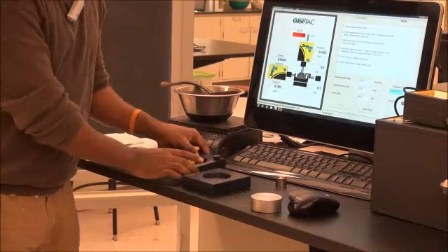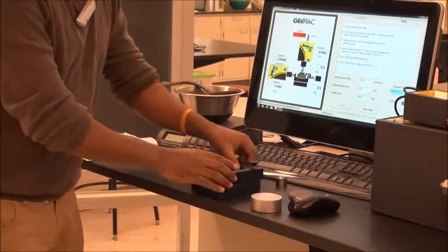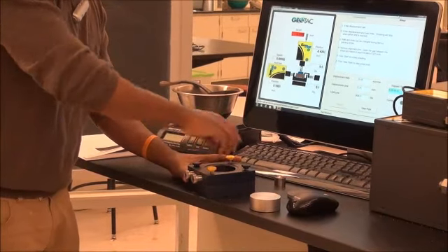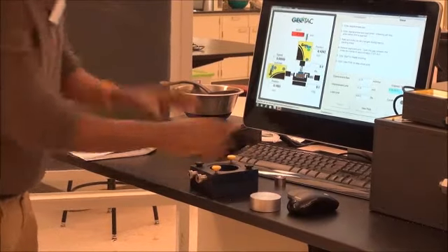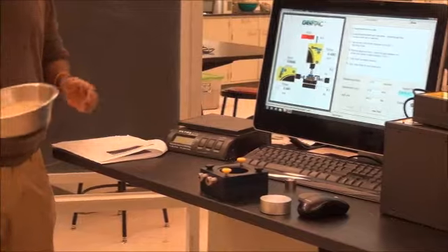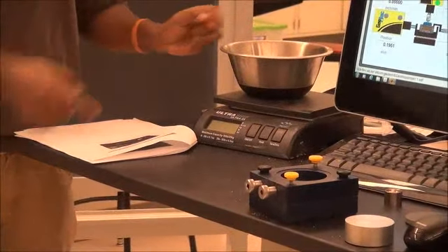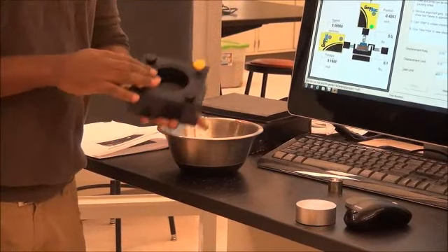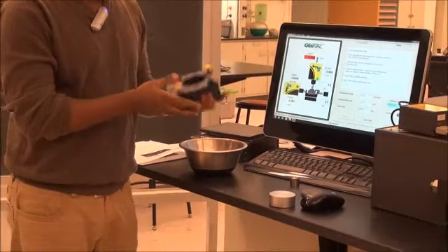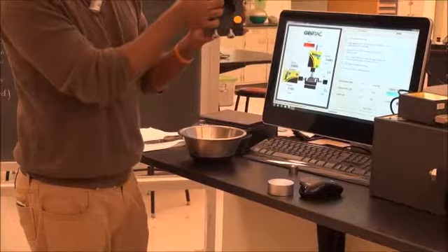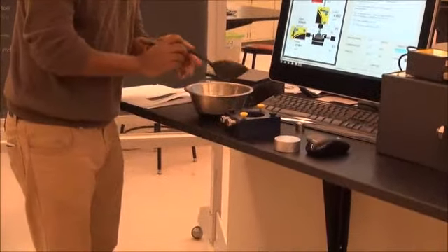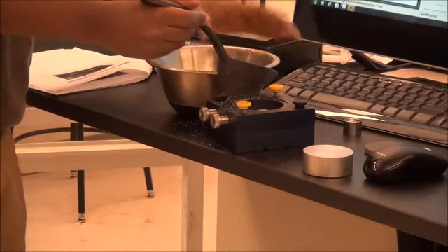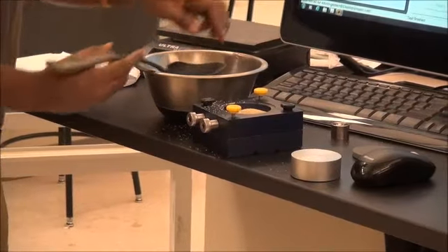The first thing we need to do is put a porous stone over here and fix it with the black screws to keep the sample in the right place. Remember that we need to take the weight of the sample and the bowl before we put some of our sample into it. We don't have to fill the soil to the top; there is a black mark over here where we need to fill the soil. You have to do this very carefully in order not to lose your soil.